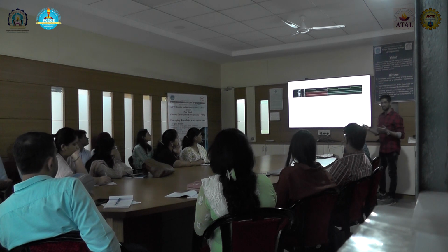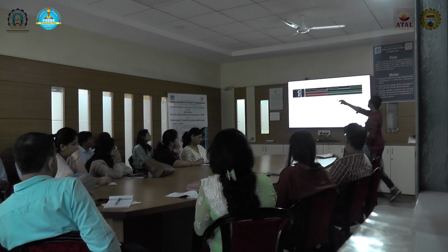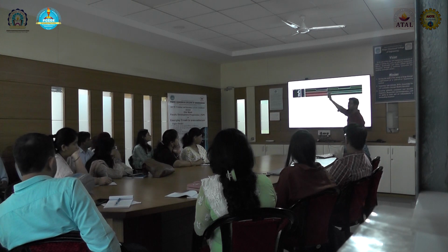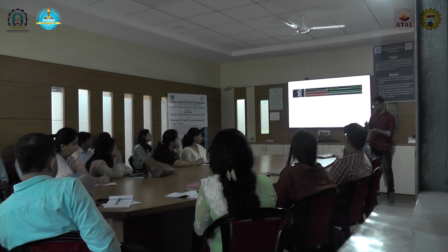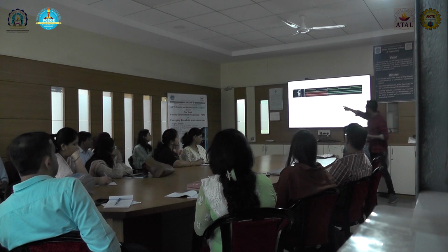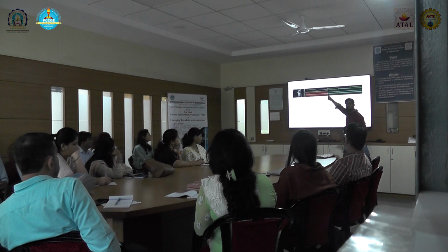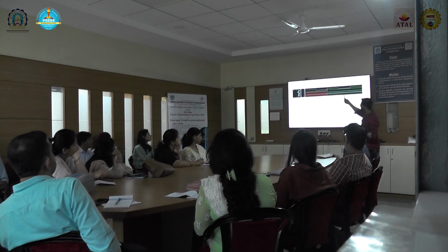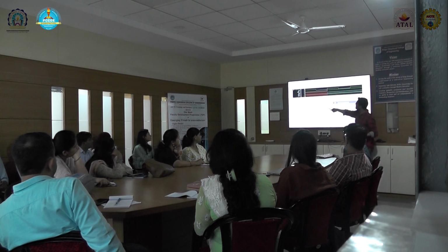After we write this property, we run formal. Formal is going to show you a trace where this property failed, because formal is used to check the behavior of the design, correct? We wrote that done should be high when busy is high, but you can see in the waveform we got done but busy is low. So this is not correct. There is something else wrong in this waveform.